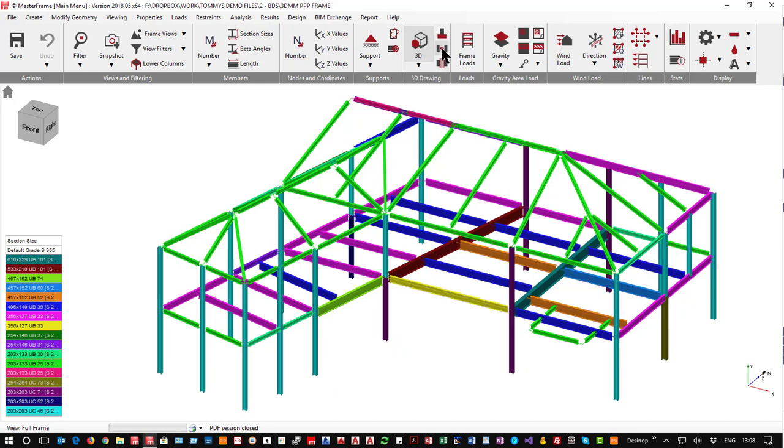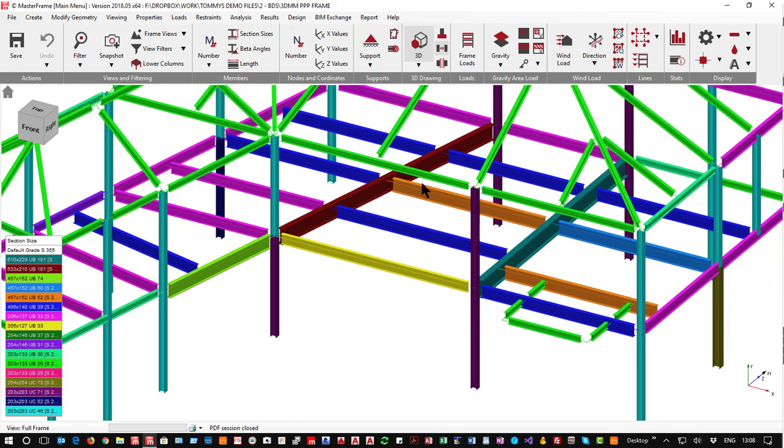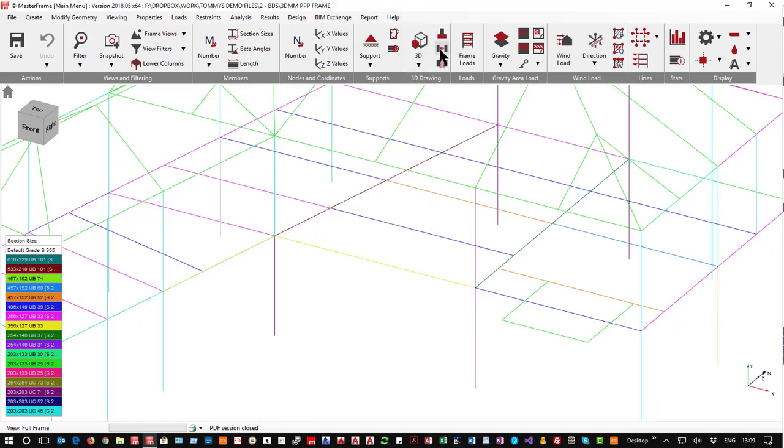Otherwise, it just shows an arbitrary, I believe, a meter by 500 or 300 deep as the pads. Draw short is very useful for seeing what is a continuous, what we used to call super member, physical member. As you can see down here, we have your physical members, and then you have component members in here, obviously, for that. Now, that's also very, very useful when you're out of 3D, because you can also still draw short and see these component and physical members where you want them. So as you can see, this big primary beam is one physical member.